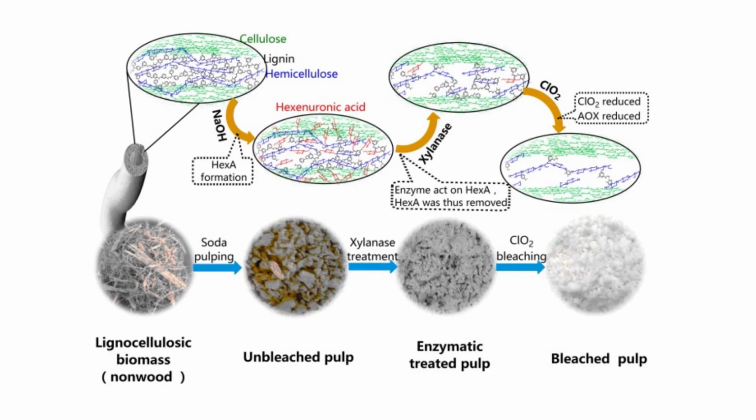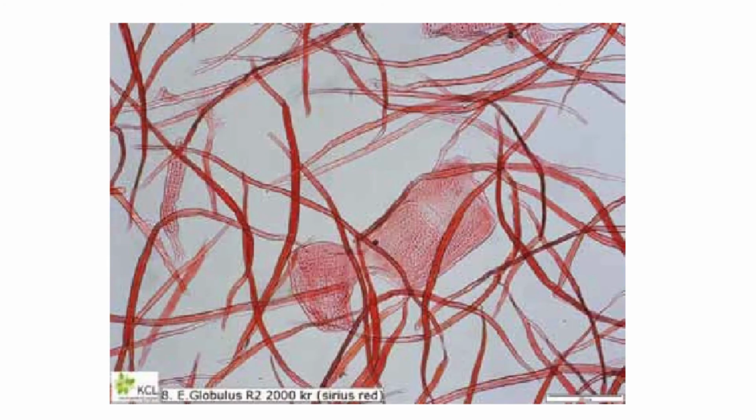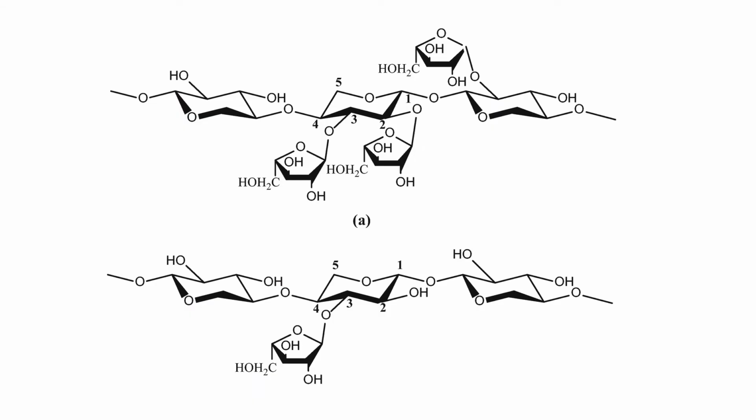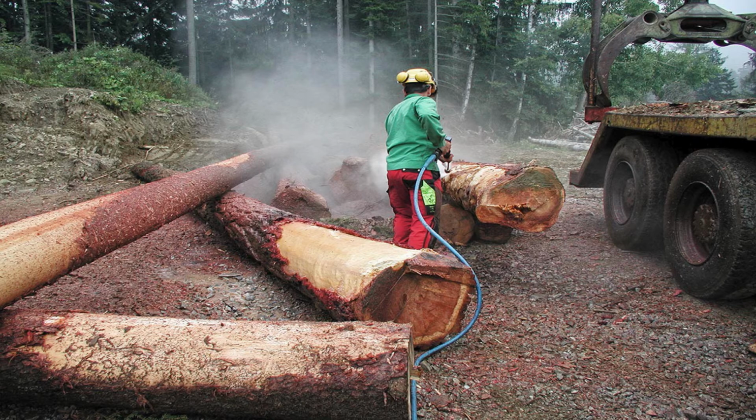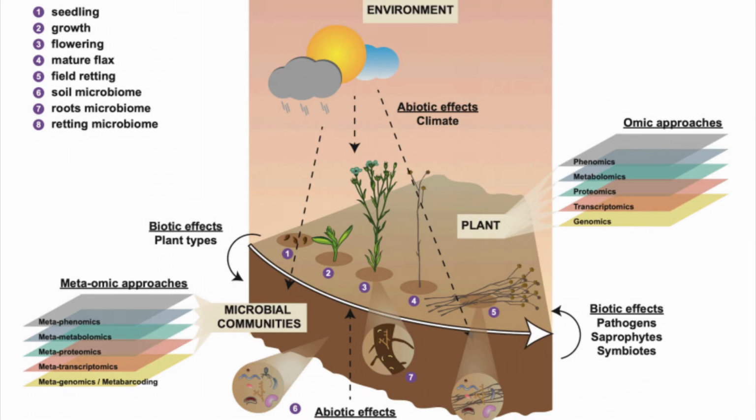Enzymes have also been used to increase pulp fibrillation and water retention and to reduce beating time in virgin pulps. With recycled fibers, enzymes have been used to restore bonding and increase freeness. Specialized applications include the reduction of vessel picking in tropical hardwood pulps and the selective removal of xylan from dissolving pulp. Enzymes have also been investigated for removal of bark, shives, pitch, and slime and for retting of flax fibers.